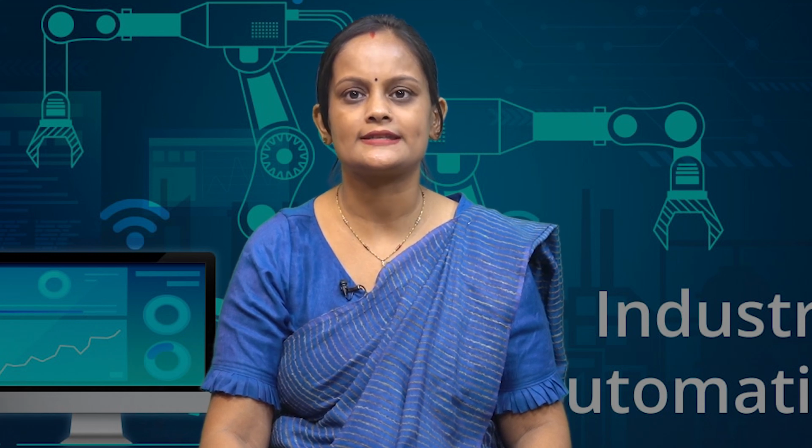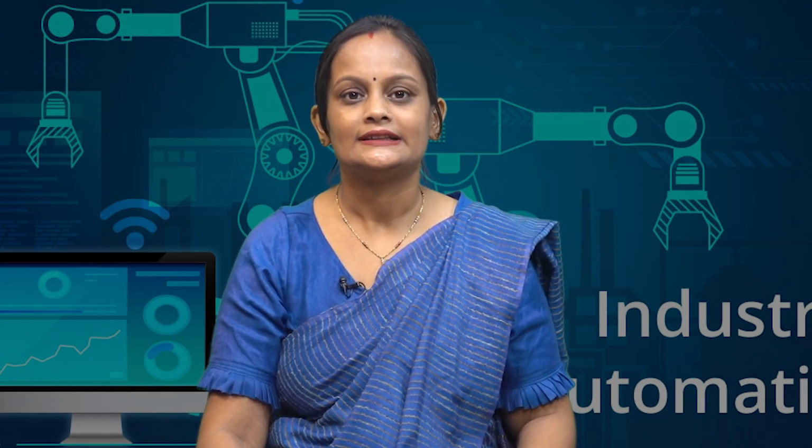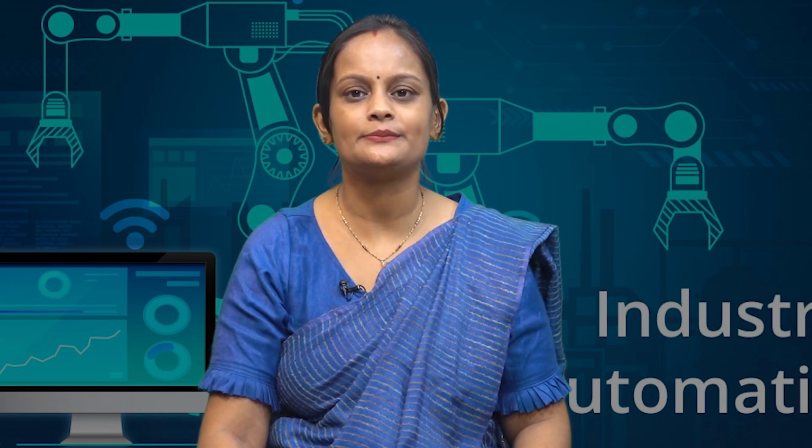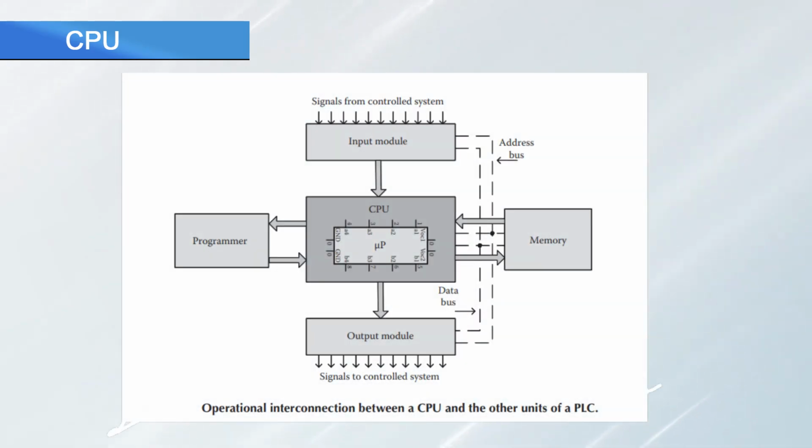The CPU architecture encompasses digital circuits for data storage and recall, as well as circuits for communication with the programming unit. An executable program stored in ROM, read-only memory, controls the microprocessor. This executable program, written in assembly language, directs the microprocessor to perform the processing, control internal units and handle the communication tasks. Here in the figure you can see the operational interconnection between a CPU and the other units of a Programmable Logic Controller, PLC.